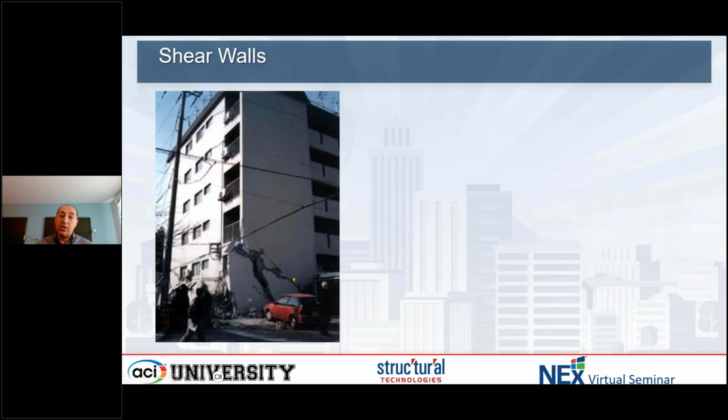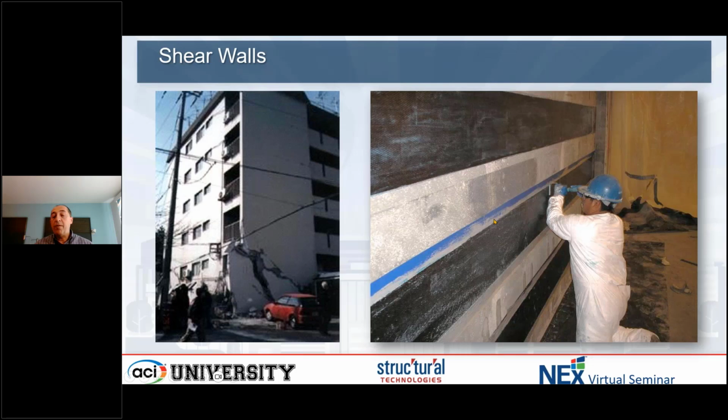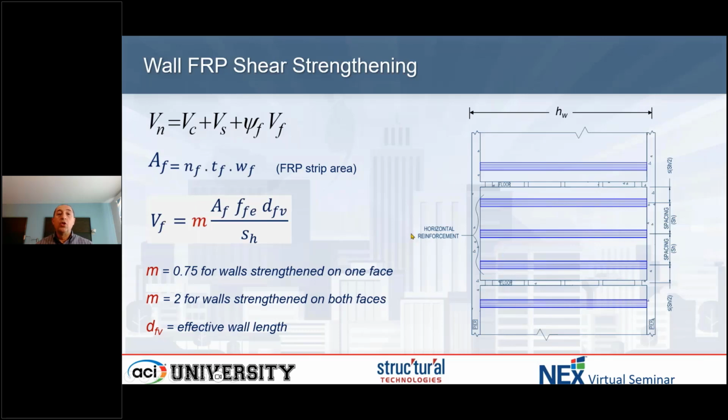Again, lower level, it's a higher shear demand in here. FRP, typically how it's used, we are trying to mimic internal shear reinforcement in a wall, which we put horizontally. Why? Because the shear now is in the horizontal direction, right? Not like a beam in the vertical direction. And the layout of the FRP may be full coverage, maybe strips, depending on the efficiency, could be on one side or two sides of the wall, right? So all these applications are viable.